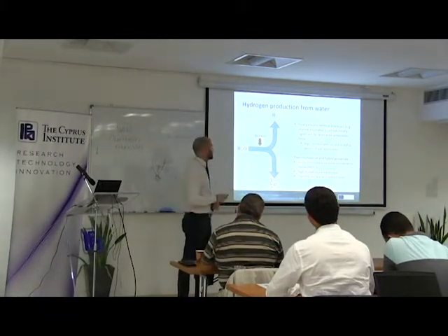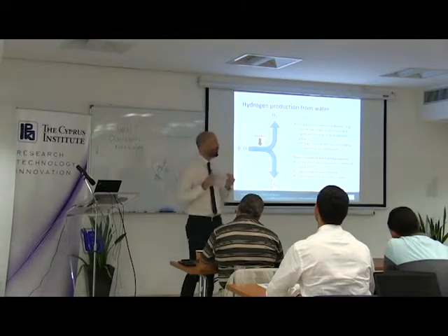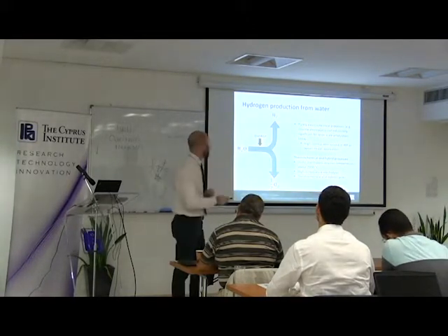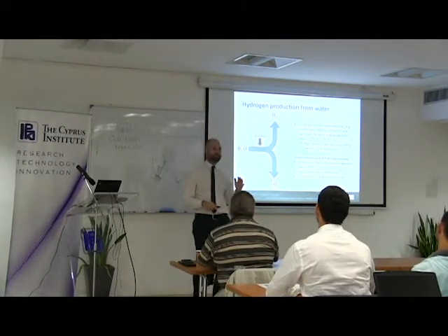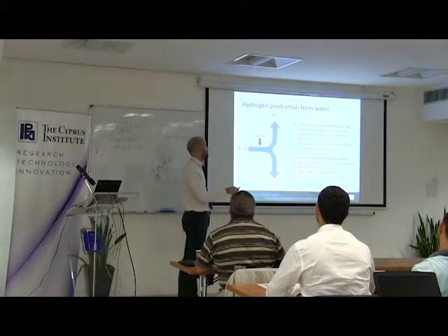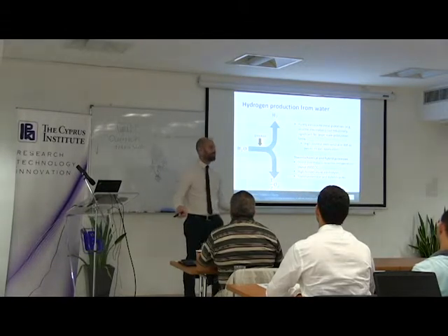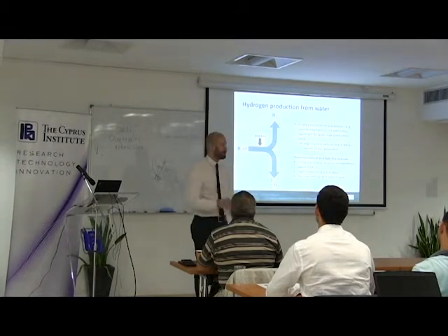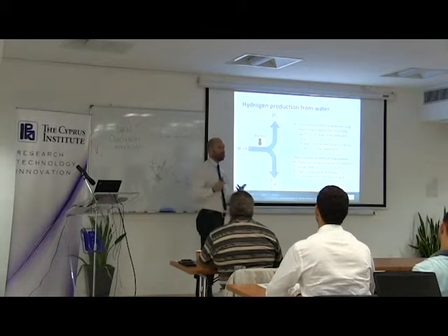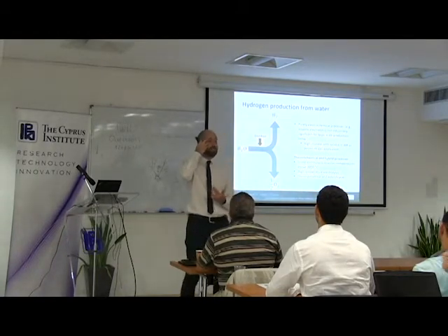However, the development of new, more efficient electrolyzers is a very active research topic now, because direct electrolysis at ambient temperature, or close to ambient, up to 100 degrees Celsius more or less, like the alkaline electrolysis process, is very interesting now that we have, as we said this morning, excess electricity production in the grid at some moments of the day. So this is being studied as a way of storing the excess electric energy produced by the non-dispatchable renewable energy technologies like wind and PV.